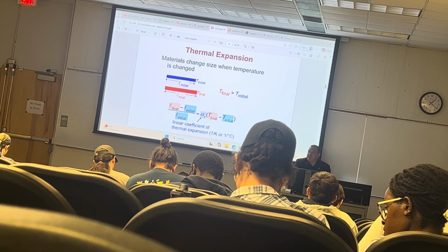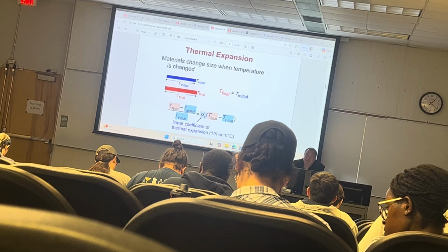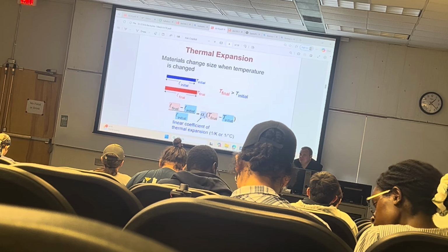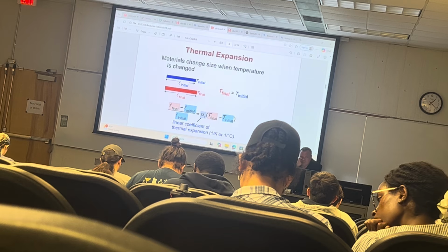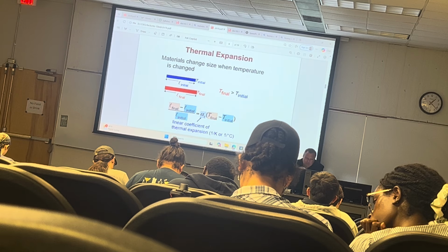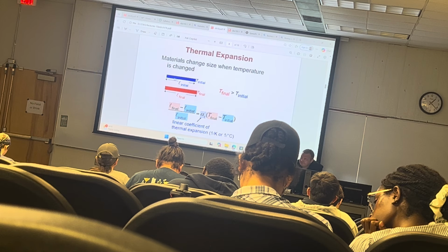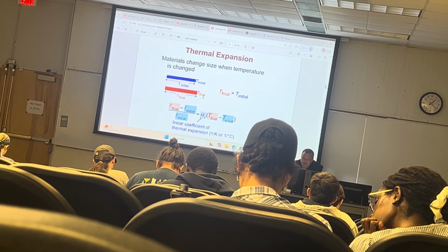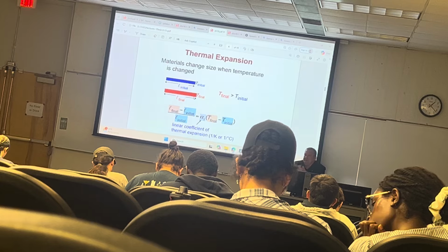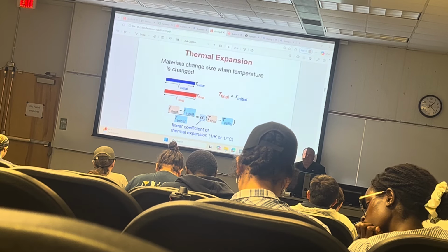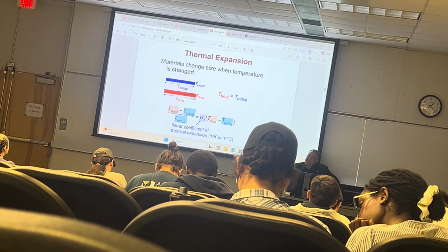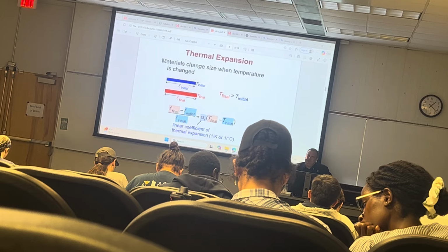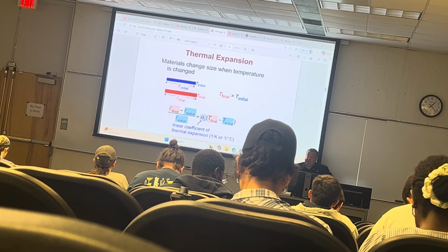And what happens during the heating is all of the materials expand. There are some exceptions, like ice. Water expands when it's frozen, but we're not going to discuss that part. So initially we had the length of your material L, and then we heated it up, and it elongated. From the mechanics perspective, it doesn't matter why this thing elongated. It means that we attain strain.